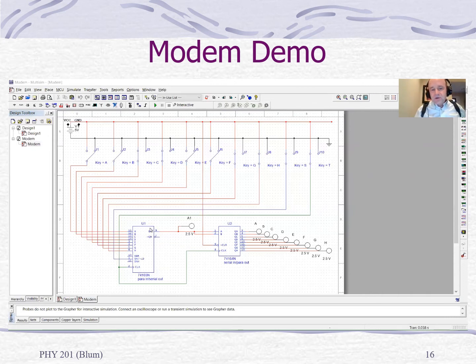And imagine this transmission line to be some long distance. So it'll come in parallel, it will travel across this line in serial, and then it will come back out in parallel. The pattern we're going to see is going to be low, low, high, high, low, low, high, high. So a pattern of 2 lows, 2 highs, 2 lows, 2 highs.